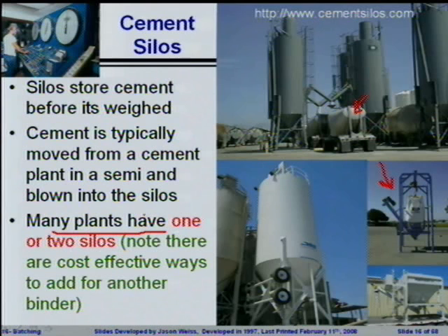One of the things that is fairly problematic at some ready-mix plants, and you should be aware of this, is the idea that to a driver, the shop vac system for cement looks exactly the same as the shop vac system for the fly ash. If you get your fly ash and cement backwards, it's a big deal. And this happens frequently enough that it's something you need to be very concerned with.